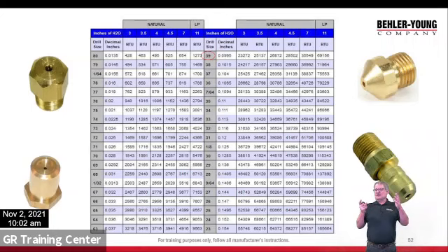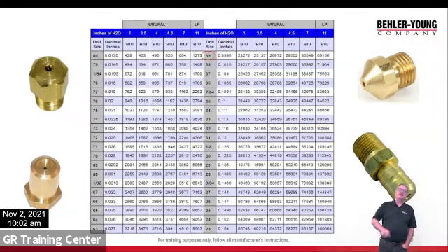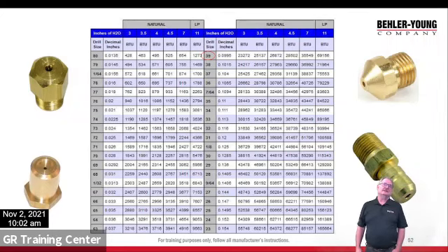If you ever needed to drill them out, typically we don't do too much of that anymore. You just buy new orifices. But you'll see there's 35, 38, 36, 37, 30, and so on, the different size orifices. Now, across, it'll say what it is in decimal inches. So that 35 is a 0.0995.